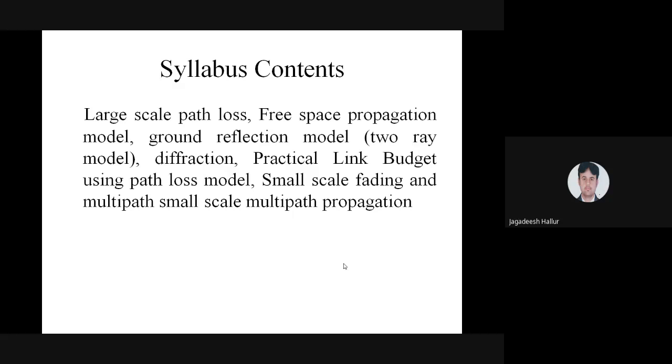In it, we are going to calculate the total received power at the receiver end, that is P_R. P_R is calculated from several parameters: the transmission power, the transmission gain, the received gain, the distance between the transmitter and receiver, the wavelength, and the frequency band.